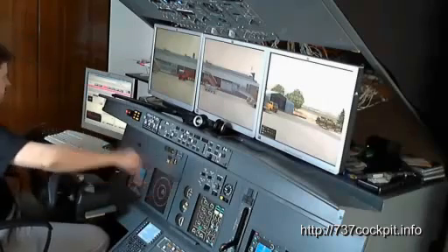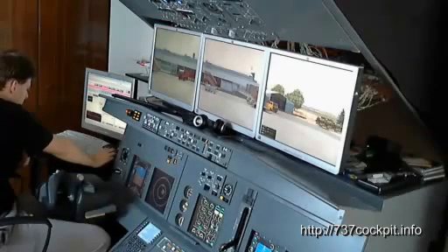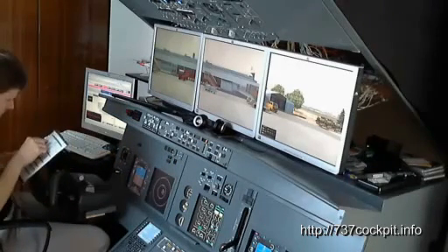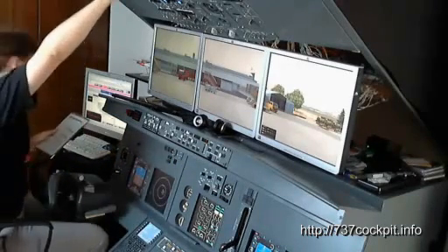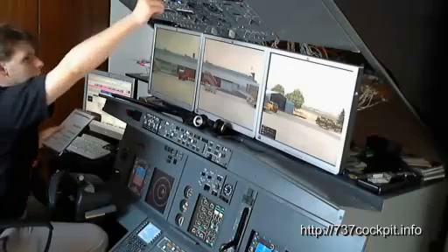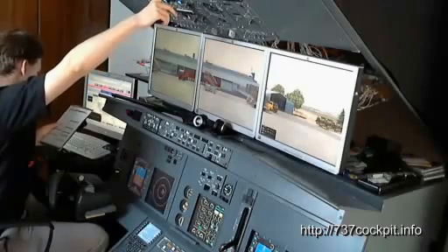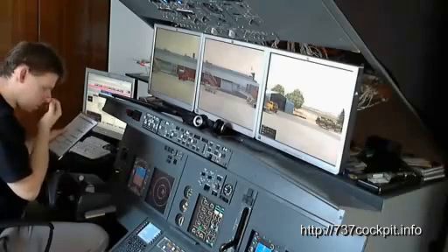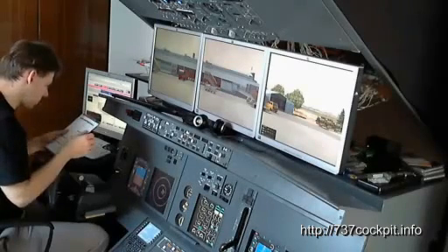So with the light test, I can see that all the lights and required lights are working. Navigation IRs is already calibrated. Galley power is set to on. Emergency exit lights are armed. Internal and external lights as required. We will switch it on afterwards.